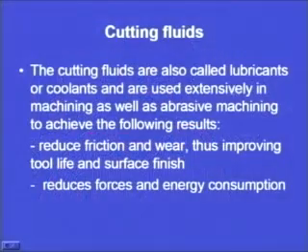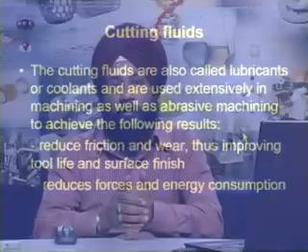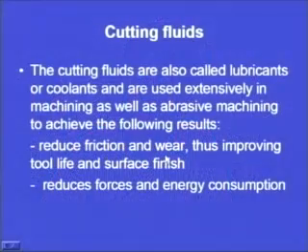for our intended application. So, the cutting fluids, also called lubricants or coolants, are used extensively in machining as well as abrasive machining to achieve the following results. So, why are we going to use a cutting fluid? Either it will be acting as a lubricant or it will be acting as a coolant. So, why is a cutting fluid required? It reduces the friction and wear, thus improving the tool life and surface finish. So, when the wear is reduced, the tool life will increase. So, cutting fluid will reduce the friction and the wear, and it will improve the tool life and the surface finish.